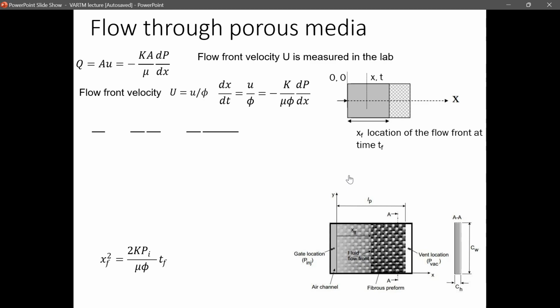At the same time, since the strands of fibers have to be away from each other to have a more porous material, you're going to have a weaker material, not as strong as you want it to be. So there is always a balance between the porosity and the strength of the material. They are not directly related, because porosity comes into play when you are doing a fluid dynamics and fluid mechanics analysis, but they can affect each other.